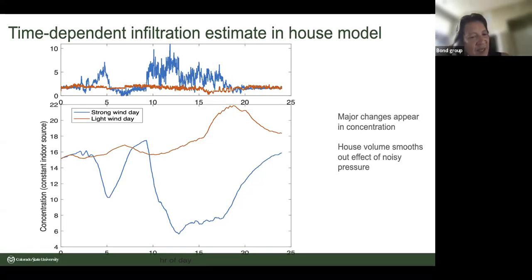Okay, so the last thing I want to say, I don't have another slide, but the goal of the tracer gas measurements is going to be going backwards from a constant injection of tracer gas. So you'll see a change in concentration, and then theoretically you can back out what the total infiltration is during that time. And so then we can confirm whether the infiltration model that we have is accurate. So what you've seen is going forward. Then when we start with the tracer gas, we're going to go backward through that process.